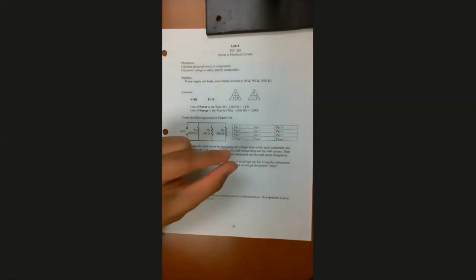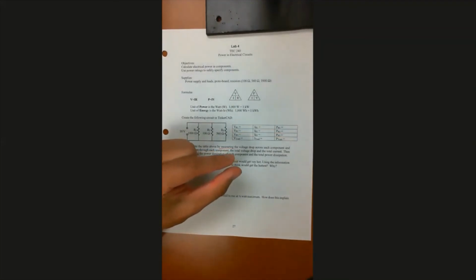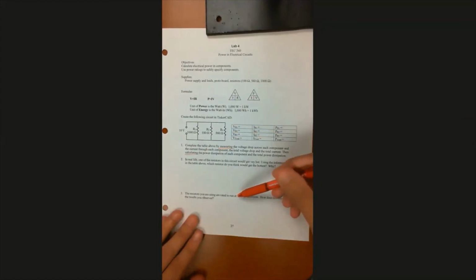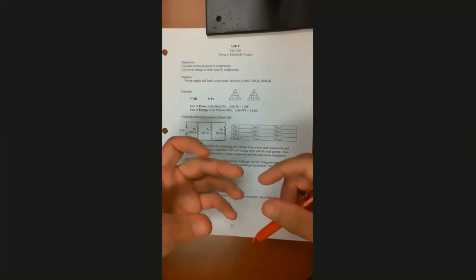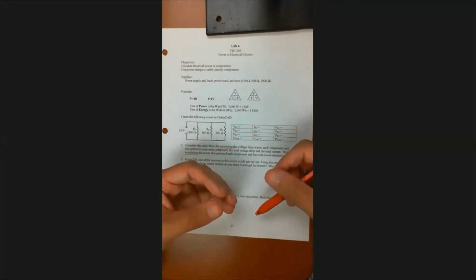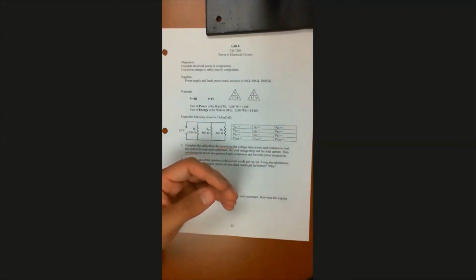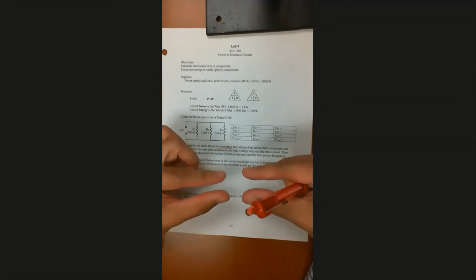So 1/8 watt resistors are really tiny. They're little bitty resistors. No matter what the actual resistance value is, they're all really tiny, and they're not designed to dissipate much heat before they just get too hot. Eventually they could actually catch fire if you left them energized for too long. As you get larger and larger power capacities, they're just physically larger. They're more robust. I've got a bunch of 10 watt and 20 watt resistors in my lab, and they're pretty big, so they're capable of dissipating more power without destroying themselves.